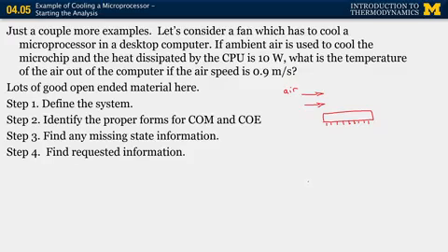We're asked what the temperature is out of this heat exchanger type system. So in this case, my heat exchanger is the heat that's being dissipated from the microchip. So this is heat out of the chip and into the air. Those are the 2 systems I have that I could consider. And if I want to know what the temperature of the air is, then I have to consider the air as the system. And I think that might be very intuitive and obvious, but it isn't always.